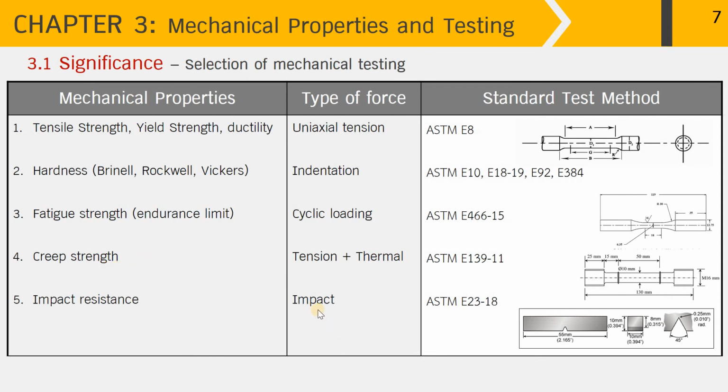And finally, the impact test. Normally this kind of test will be carried out for materials that are subject to brittleness. And if you have a look at all the specimen types, you can see that the tensile, fatigue, and creep specimens are in common shapes like a dog bone, and then you apply the load at both ends. But for the impact specimen, we have to simulate the notch as the defect on the test piece, and I will give you some more detail about this.